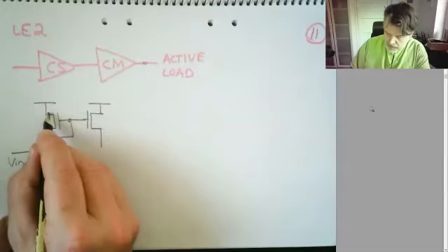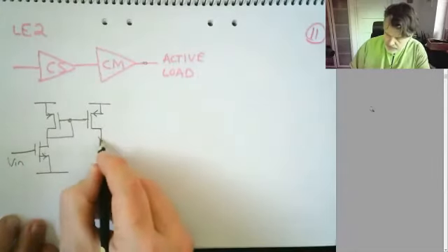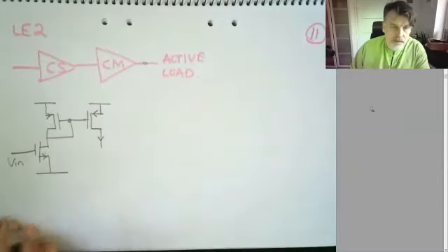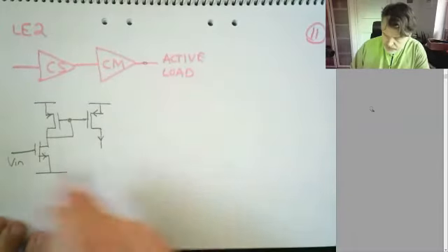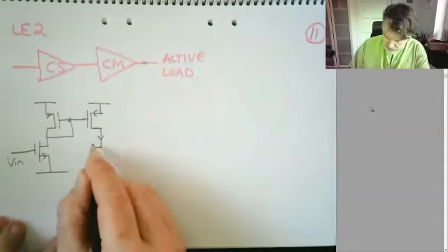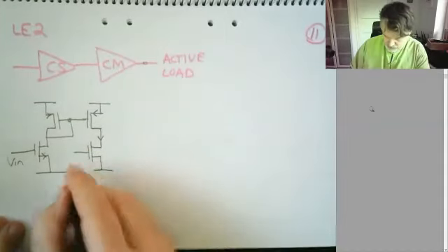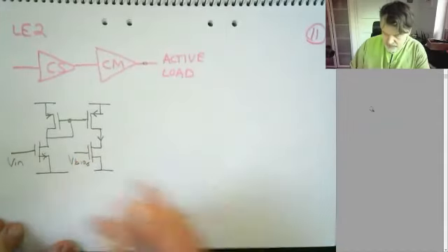And as we see now, there's an output current coming here, but it's not terminated anywhere. So we have to convert this into voltage. There are different ways we could do that, but obviously, something like this would make sense. A bias voltage, like an active load.